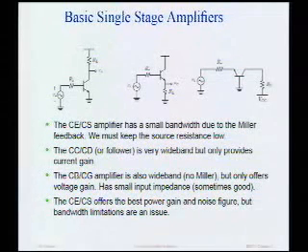What about the bandwidth of a common source amplifier? Well, the bandwidth is very good. It's a very wideband stage, and that's because there's no Miller multiplication. You can see the voltage gain from here to here is 0 because I've grounded this node, so the Miller capacitor just appears in parallel with the input. The device capacitance, let's say C pi, is in a sense bootstrapped.